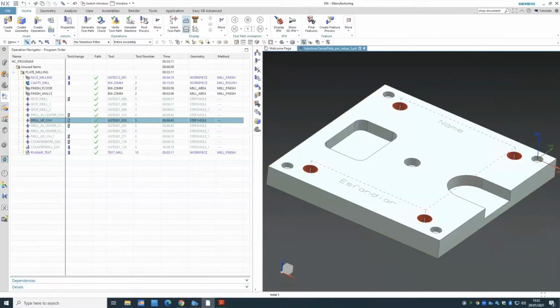Yeah, Charlie. So if the diagonal ones are faster, I thought 1, 3, 4, 2, because then you have 2 diagonal ones and only one vertical one. So is that the right way to look at it, or am I missing something? Well done. Yes, but also you need to consider Z movement as well, because the tool needs to come up to make sure it doesn't hit it and go down. So you have those kind of moves. Not unnecessary, they're related to that one as well.